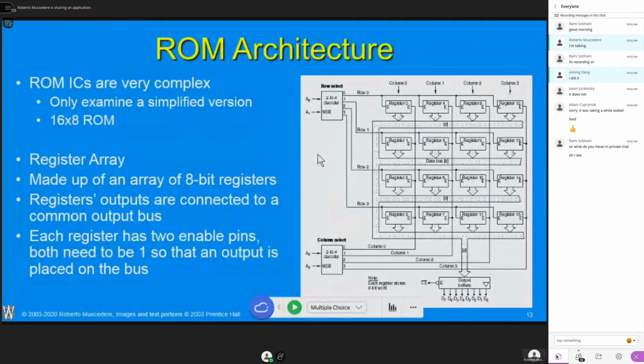These are smaller decoders, 2 to 4 decoders. What's important about this is that if a 2 to 4 decoder has a size of, let's say, 1 unit, a 3 to 8 decoder is going to be at least 2 units in size, and a 4 to 16 decoder is going to be 4 units in size. So a single 4 to 16 decoder, being 4 units, is certainly much larger than two 2 to 4 decoders. So this is the preferred method.